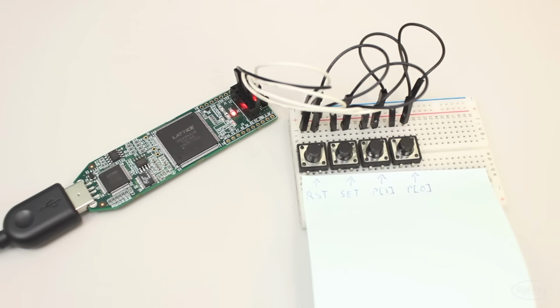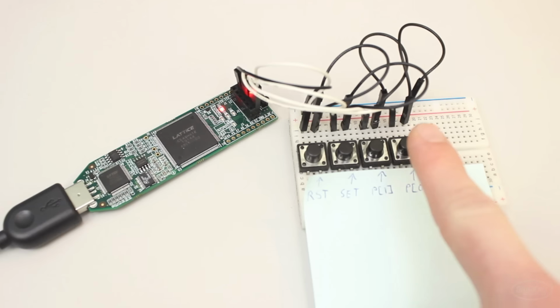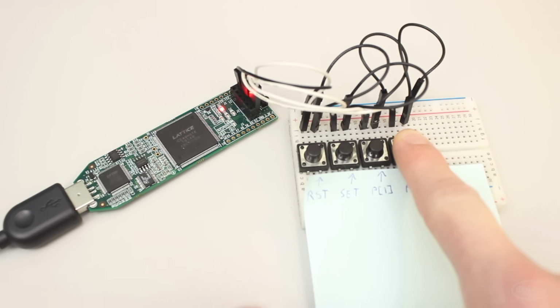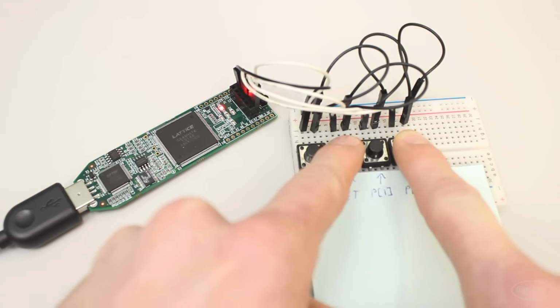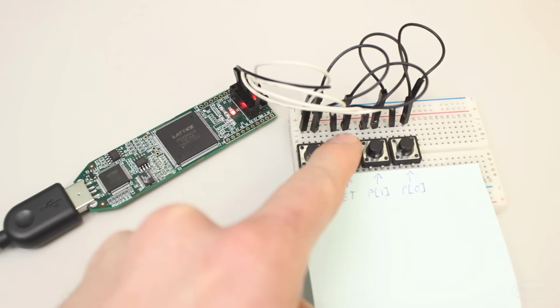Your challenge is to make a super basic LED sequencer. Don't worry about producing sounds. At each step or time tick, say every second or half second, the FPGA displays a 2-bit value on the LEDs. I'll hold a 2-bit value on my pattern buttons and press the Set button. This will log the pattern 00 from the 2 buttons on the right into the first memory element.